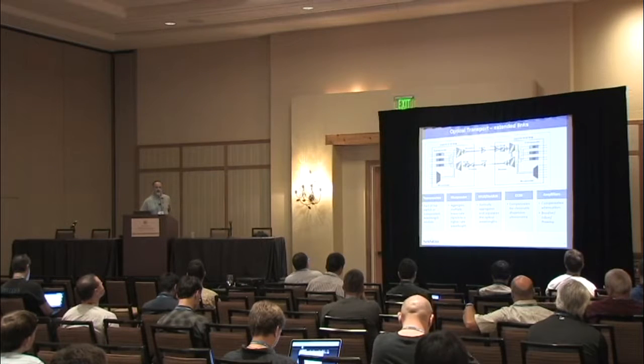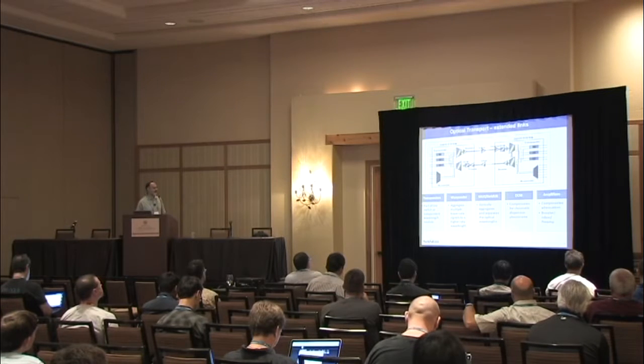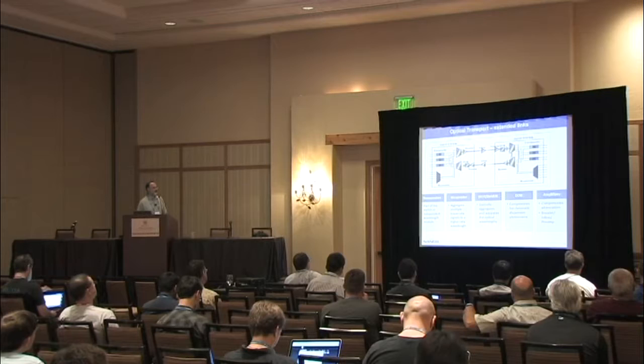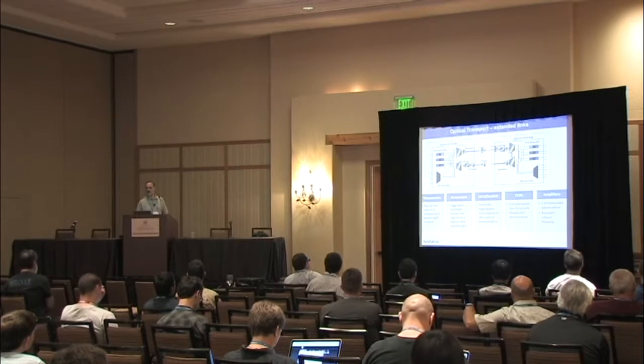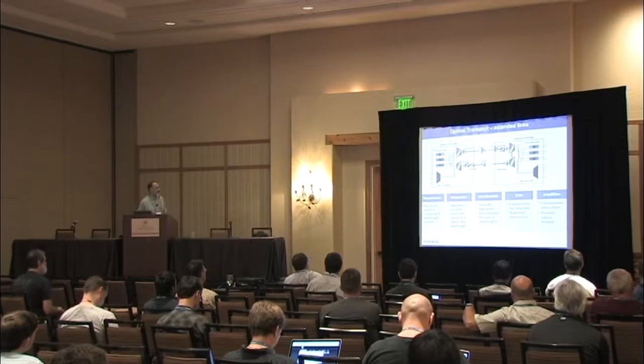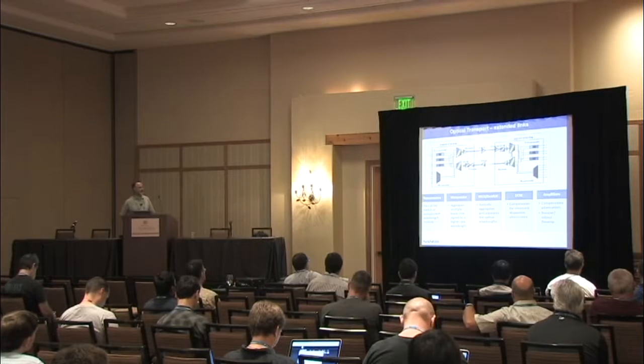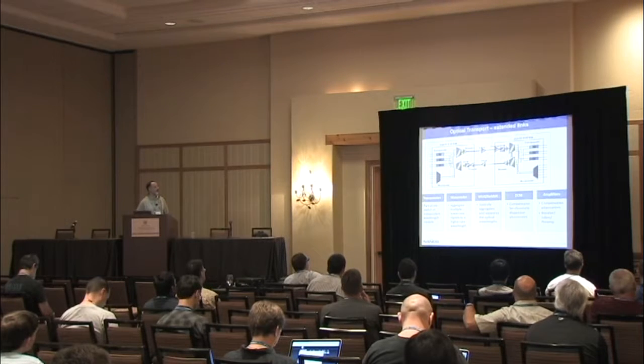We talked about compensating for dispersions, and that's the DCM. And we have the amplifier that compensates for attenuation and gets our optical budget to a higher level. Based on the position, and you see the picture there, you have at the beginning of a link a booster optical amplifier, then in the middle it's called an inline, and then just at the edge of the link you have a preamp, and you have there the DCM before or after the preamp.